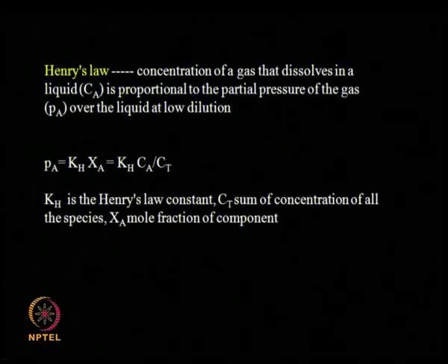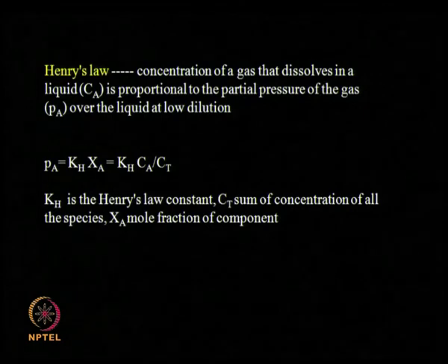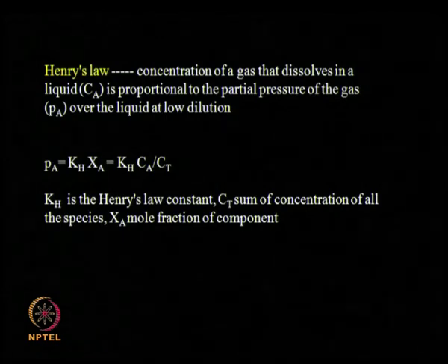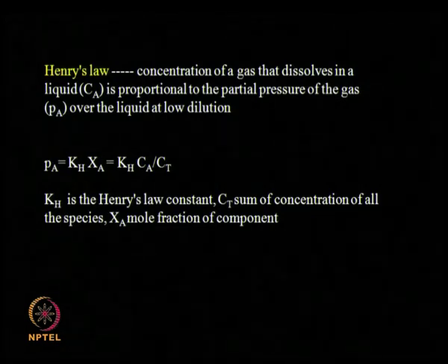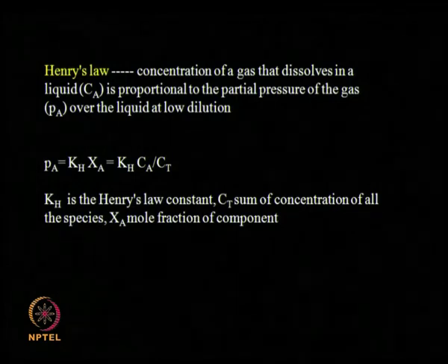Okay. Now in order to understand the concept of absorption, we should know something called the Henry's law. Henry's law gives us an idea about the partial pressure of the gas in the vapor to the concentration of that particular compound in dissolved form in the liquid.